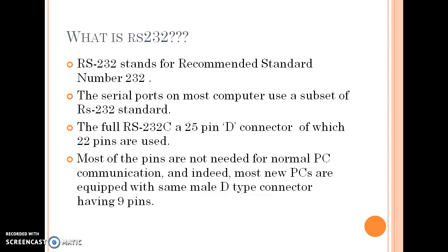It is not necessary to use all the 25 lines every time. Depending on the application, we can use a certain number of pins, and most of the pins are not needed for normal PC communication, and most new PCs are equipped with a male D-type connector having 9 pins.